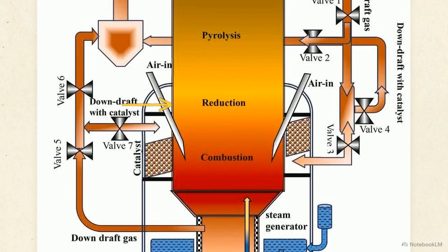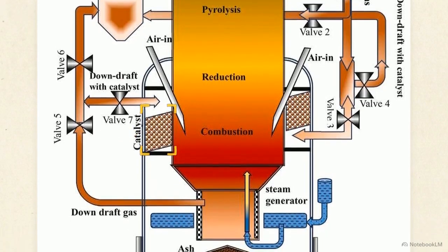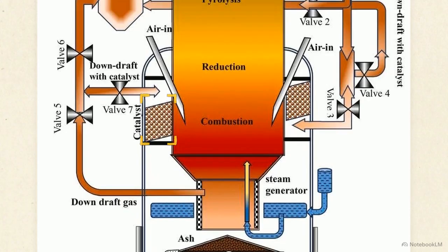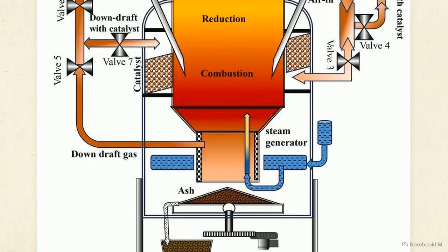This forces the hot downdraft gas out of the main reduction chamber and pushes it directly through the dense catalyst bed. As the gas permeates the demolition waste, a carbonation reaction occurs. The calcium oxide actively binds to and captures the carbon dioxide in situ. Simultaneously, the porous, high-temperature concrete surface provides active sites that thermally crack passing heavy tars into lighter combustible gas molecules.